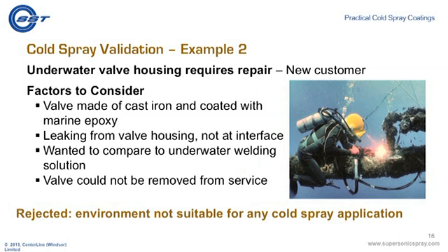Let's use another example of a cold spray validation process. We had a new customer contact us and he wanted to repair an underwater valve housing. Typically he's using underwater divers equipped with marine welding technology. The valve here was made of cast iron and it was coated with marine epoxy. There was leakage from the valve housing but not at any particular flange interface. Customer wanted to compare cold spray application to his current underwater welding solution. And this valve could not be removed, repaired, and placed back into service. It had to be repaired in situ.